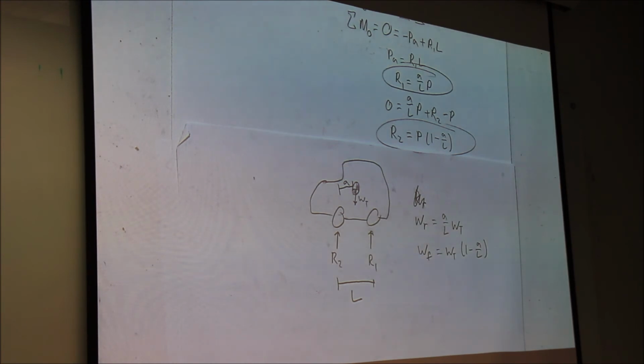Depending on how much time I had, I wanted to go over moments of inertia. I don't know if we're going to have time for that. Instead, there is one thing that's kind of important, which is boundary conditions, especially when you start doing FEA. A lot of times, even in industry, FEA, or finite element analysis, which is basically a simulation of the part undergoing forces, they have to redo over and over again, sometimes because they get the boundary conditions wrong. It's a really important part of how this thing would behave.